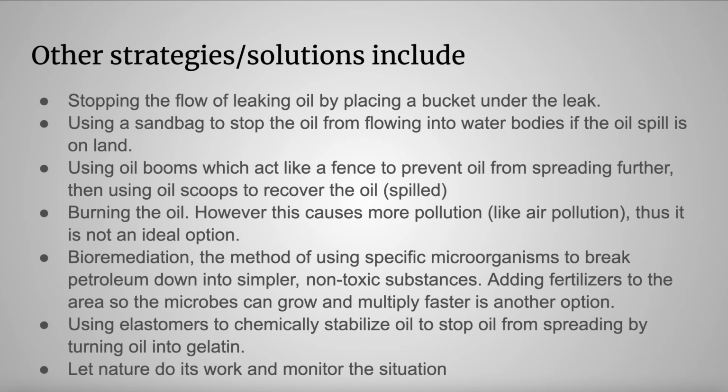Other strategies and solutions include stopping the flow of leaking oil by placing a bucket under the leak, using a sandbag to stop the oil from flowing into water bodies if the oil spill is on land, using oil booms which act as a fence to stop oil from spreading further, then using oil scoops to recover the oil, and burning the oil. However, this causes more pollution such as air pollution, hence is not an ideal option.